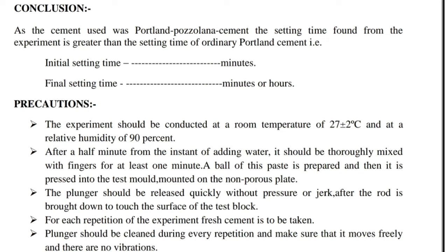Precautions: the experiment should be conducted at a room temperature of 27 ± 2 degrees Celsius and at a relative humidity of 90%. Next, after a half minute from the instant of adding water, it should be thoroughly mixed with fingers for at least 1 minute.